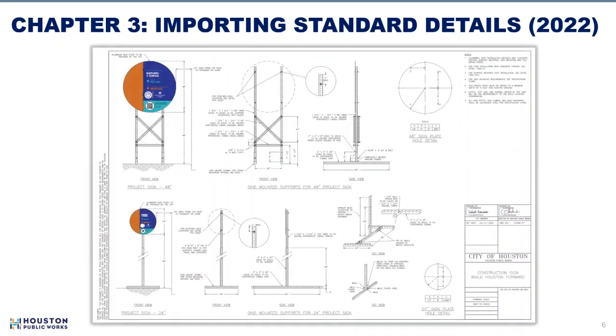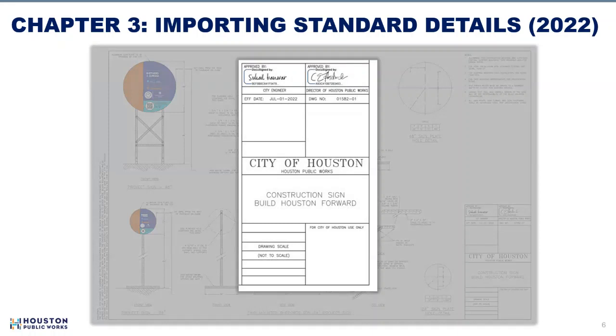The title block has been created to mirror the capital project standard title block. This is done so that the standard detail does not have to be shrunk within a project title block and can be printed on a full ANSI D sheet. The project information has been left blank within the title block to allow for project-specific info to be added by the consultant in CAD.